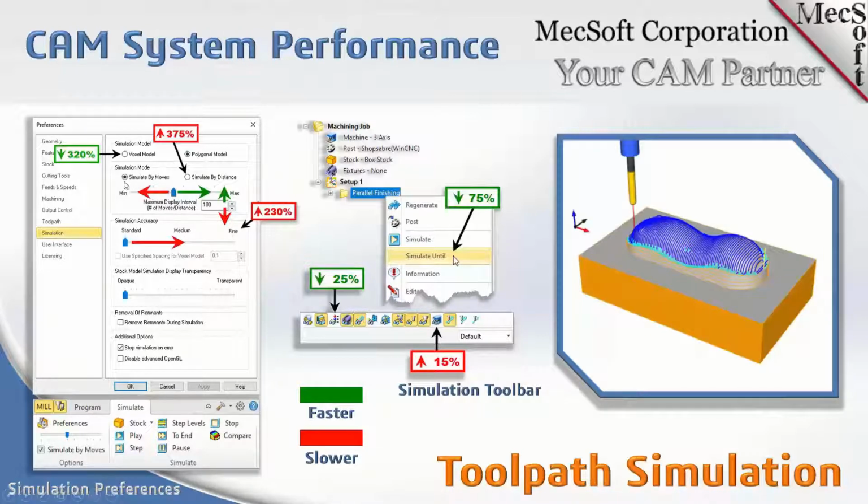Now, you've got two choices here, simulate by moves and simulate by distance. What this means is how many times that model gets refreshed on your screen. In the background, the algorithm is calculating all the toolpaths and going through all the model, but you can control how many times it shows you the model during the time it takes to generate the simulation model. If you don't care to see the toolpath 5 times versus 35 times, you're going to really decrease the amount of time it takes to get through that simulation.